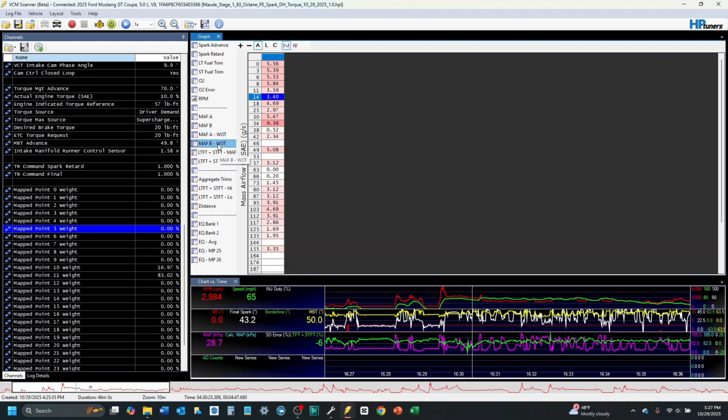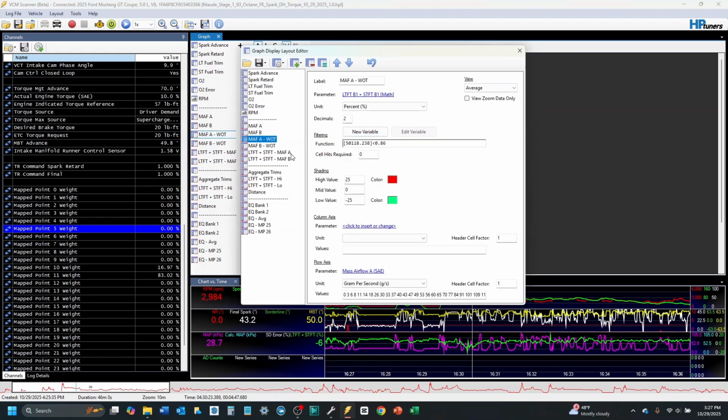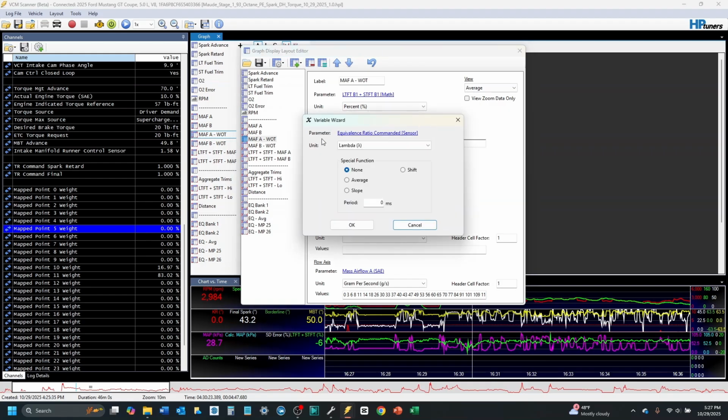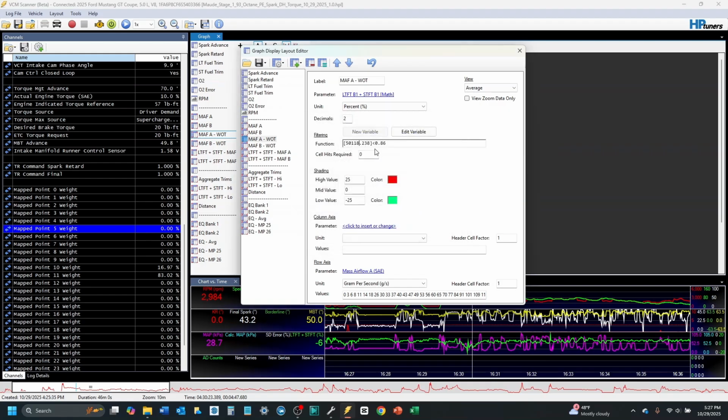And I'd rather not put watt miles on the car right now for the sake of cleaning that up. That looks pretty clean. That's a little sketchy, but again, it's under 5. And then this one's clean as a whistle, right? And if you look at my filters, EQ, lambda. So for lambda, what I'm saying here is only show me data where the commanded lambda is under 0.86, which corresponds with when we're wide open.